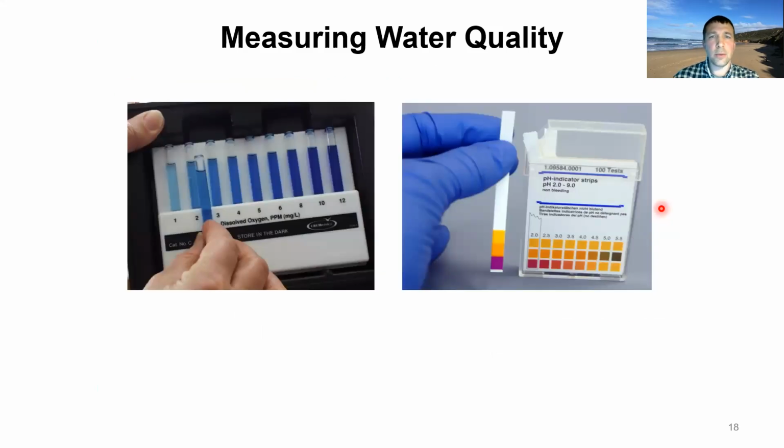Some other tests that we can use to measure a variety of parameters consist of colorimetric methods. Things like dissolved oxygen or even nutrients like nitrate, ammonia, and phosphate can be measured colorimetrically. If we're back on campus in week 2, we'll actually do that for water at Monash University. And even things like pH can be measured with colorimetric indicators like pH paper, where you simply dip it in the water and then compare the color key to a standardized chart.